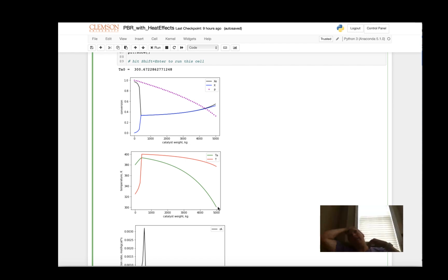I think we're taught, when we first learn about heat exchange, that countercurrent is more effective. Here's a case where, when you have a chemical reaction, that's not always true, because the chemical reaction is releasing so much heat that it's heating the cooling fluid significantly. So really, if you compare the countercurrent and the co-current heat exchangers in this case, they're operating pretty similarly.